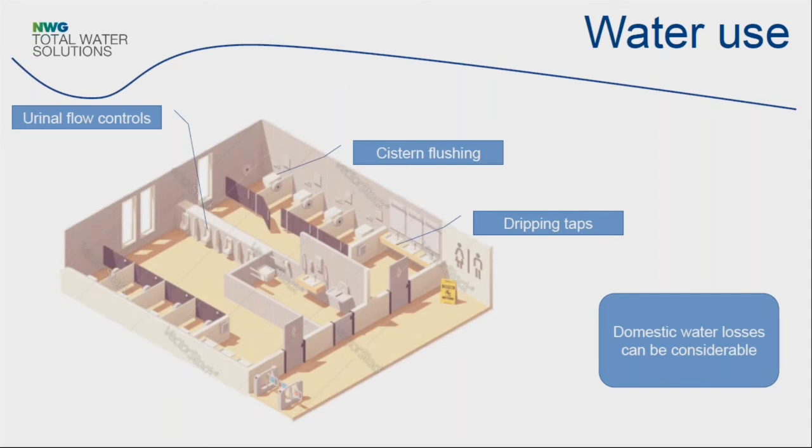And on the same site, they'd put in very water efficient taps with PIR sensors. Again, they didn't deliver a huge amount of water. So when people were using them, they were maybe operating the taps 3, 4, 5 times to wash their hands. And eventually the PIR sensors broke. So the client had a rolling programme of removing those taps and putting in push taps.